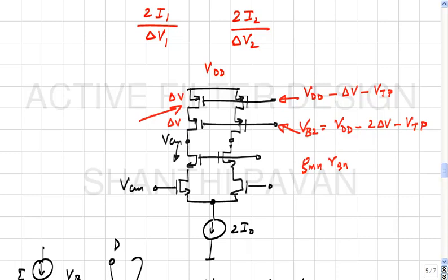You have two transistors. So you lost some of that swing already because of the extra cascode. Okay. So, it's kind of hard to fit. You can at a pinch fit two cascodes, but then you will find that the amount of headroom you have left for the signal swing has all been eaten away by the cascode.